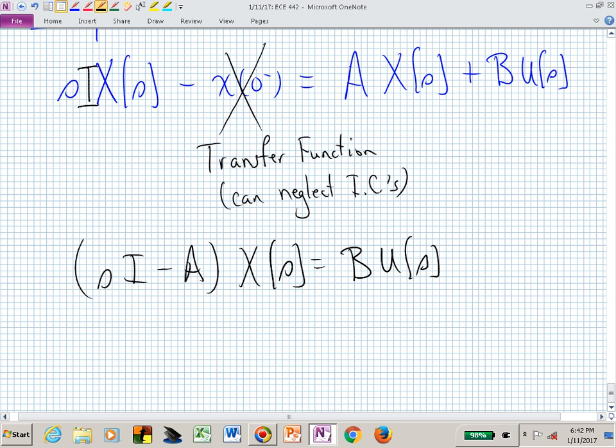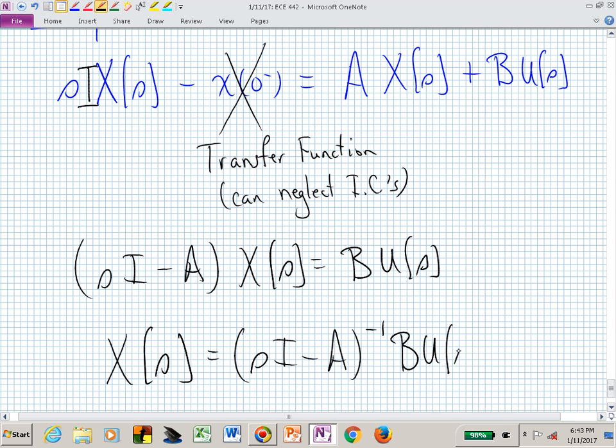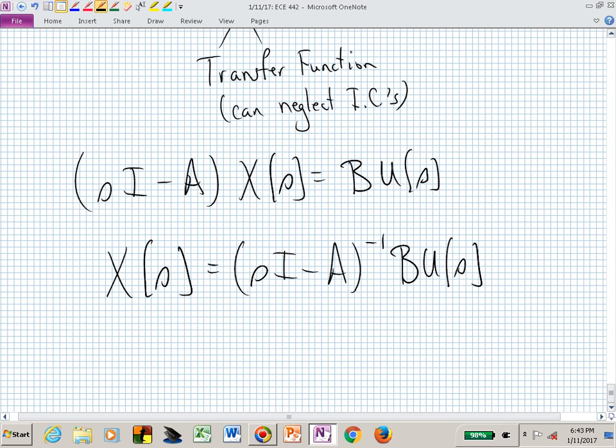And I said we wouldn't have to compute this numerically, but we could do it virtually with our equations. So let's now invert that matrix sI minus A to isolate capital X of s. And now we could do all of this in the frequency domain, and we could inverse Laplace transform the right-hand side to obtain x sub 1 of t and x sub 2 of t, which are stacked in this vector form in the frequency domain.